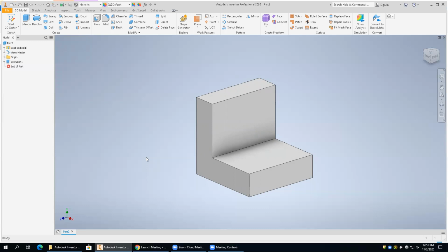We can also look at this thing in different views. Right now we're looking at what's called an isometric view. So isometric means you're taking an object, you're rotating it one direction, rotating it another, and you rotate it the same amount in each direction. Okay, that's how you get the term isometric. Iso means equal. So an isometric view is not a really true view of the way we would look at things. Okay, so if we want to see how we would look at things, we can go to this view,